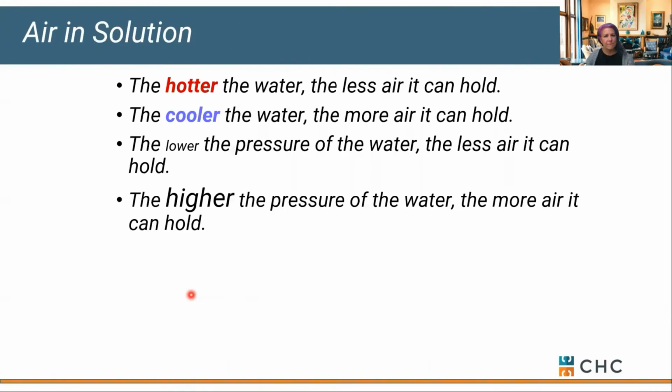Let's talk about air. If you draw a glass full of water out of a tap, you're going to start to notice some little micro air bubbles that occur, and that's a gift from the city. They give you entrained air. So we get that in our hydronic system. We're constantly dealing with air, and as water cools, it absorbs some of that air. As we heat it, it gives it up. So the hotter the water is, the less air it can hold, and the lower the pressure that water's at, the less air it can hold.